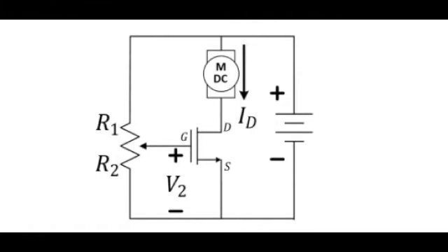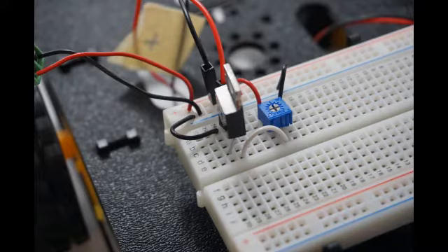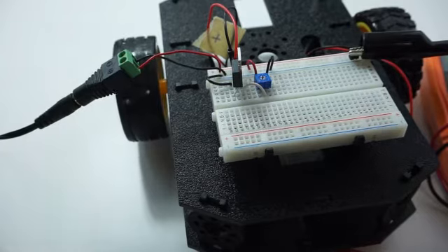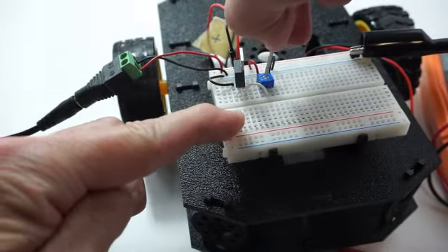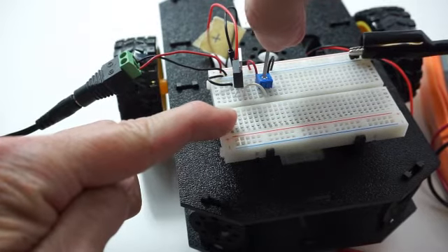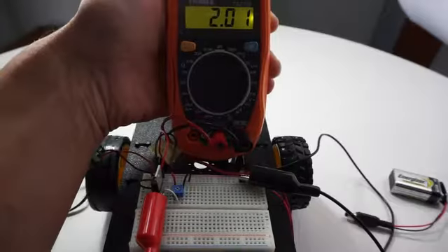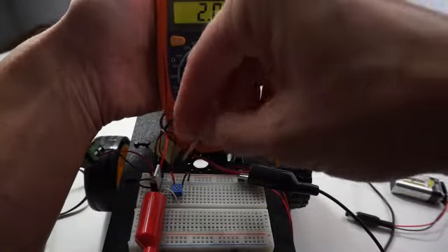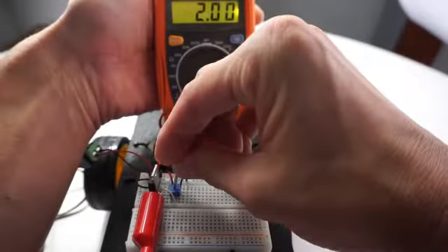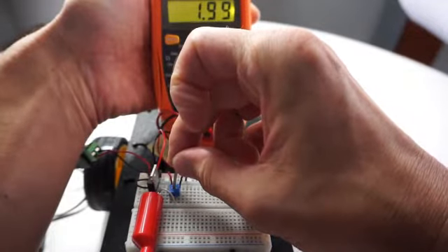Now build the voltage divider based motor drive circuit onto your breadboard. Connect power to your circuit and verify that the potentiometer can be used to control wheel speed. Use your voltmeter to determine the voltage at the gate of the MOSFET when the wheel just stops or when the wheel seems to first hit full speed.